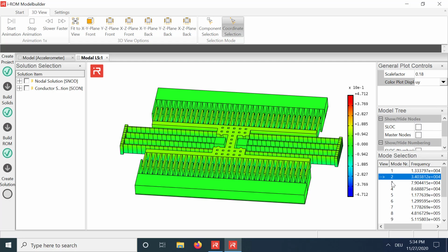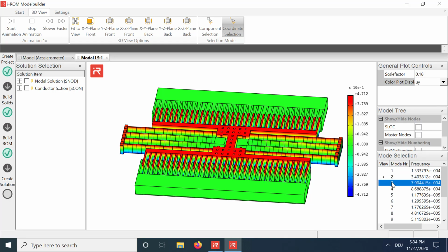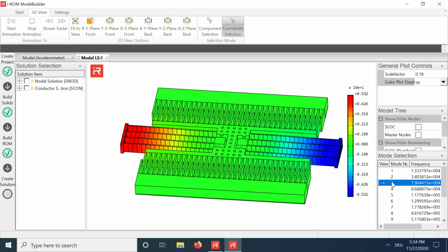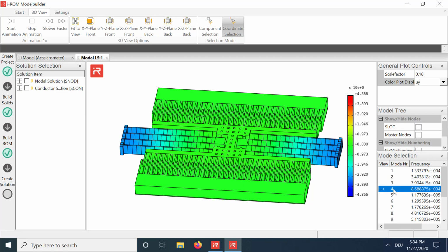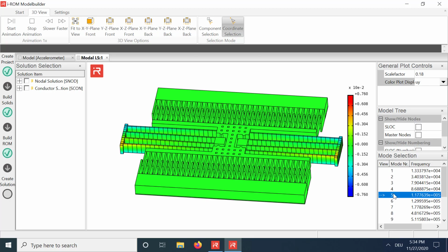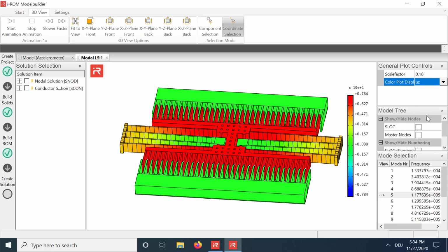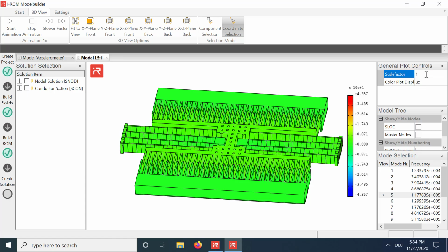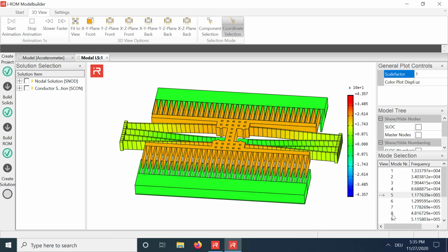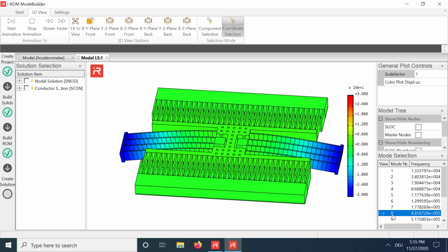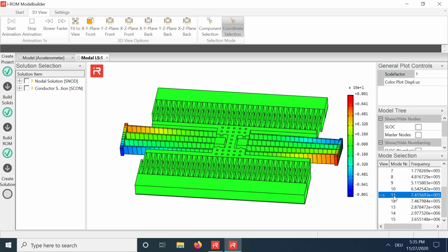Click on Other Eigenmodes, and observe the structural response. Switch to Z displacements for the out-of-plane modes. Modes 8, 11, and 13 show spring oscillations at higher eigenfrequencies which should be out of the operating range.